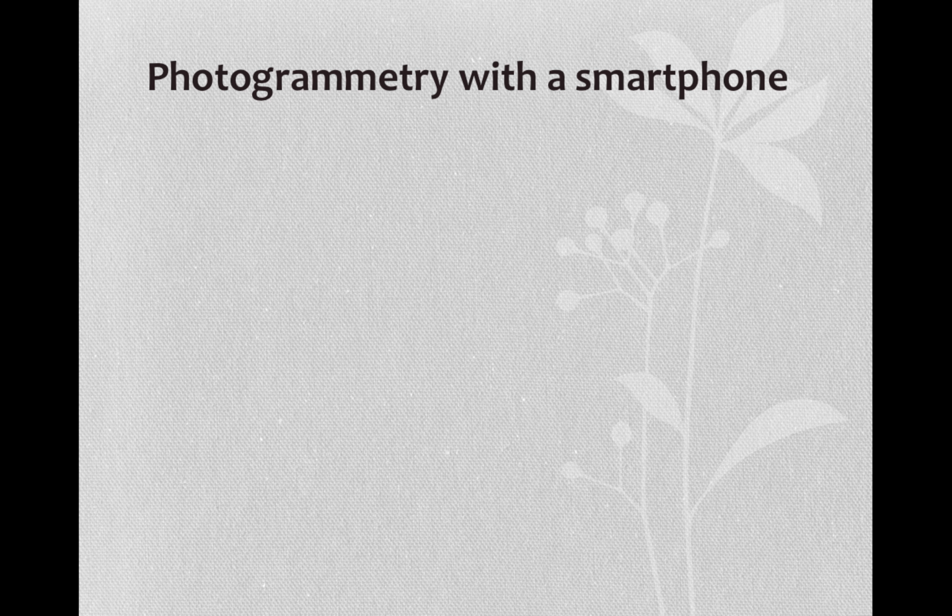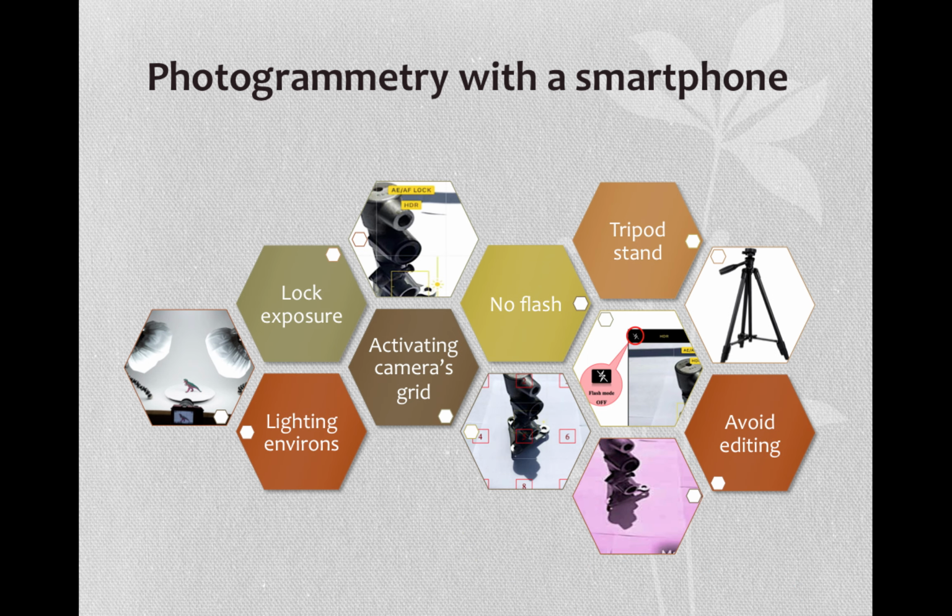Photogrammetry with a smartphone. It is vital to understand the camera placement, orientation, and lens characteristics for better image acquisition for proper 3D modeling. It is advisable to experiment with the object in a fully closed room where it does not create contrasting lighting effects or shadowy gestures. Also, ensure that the object is placed at the center of the camera frame, which occupies relatively about 70% of the examined object within a full frame.